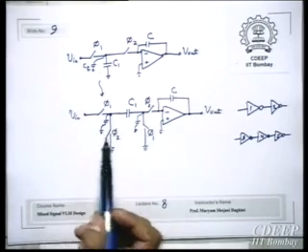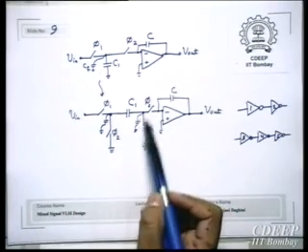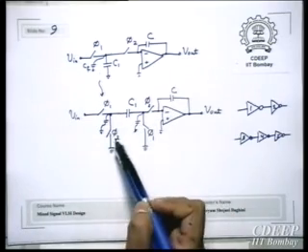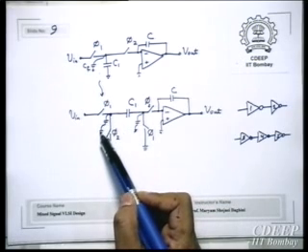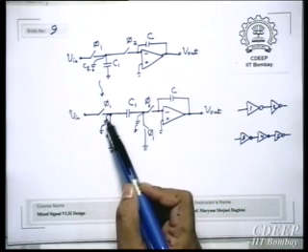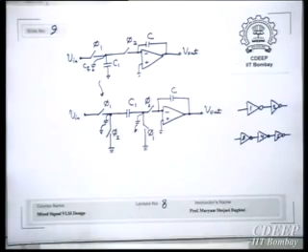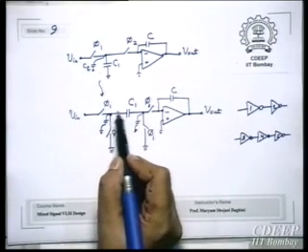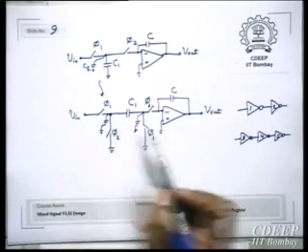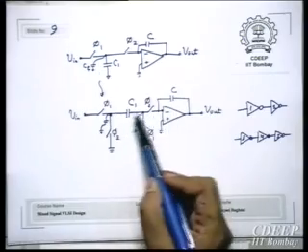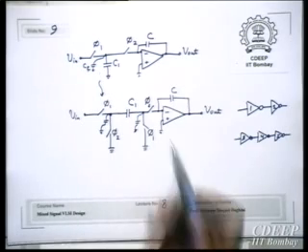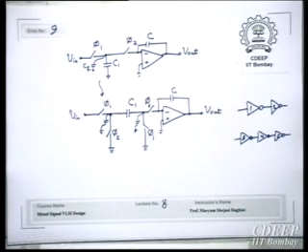But then in the next phase, when we want to transfer it to C, we close this switch. Therefore, the charge which was stored here will get discharged completely. And when it gets discharged, the same charge which has gone here also will come back to the ground path. Therefore, what goes here will be the net amount of voltage which was stored on C1 at the beginning. If you remember, we had this in the VLSI lab also. I think I asked you to simulate the same circuit.